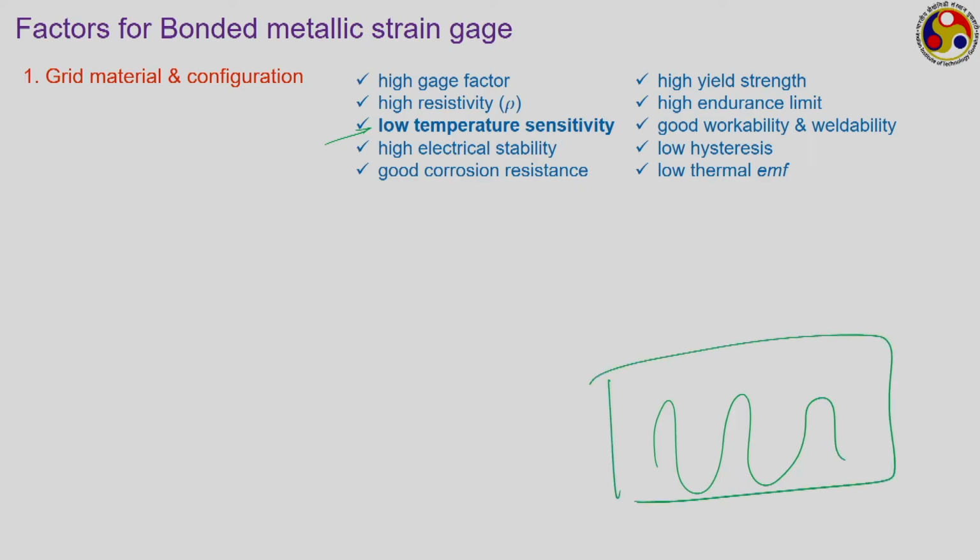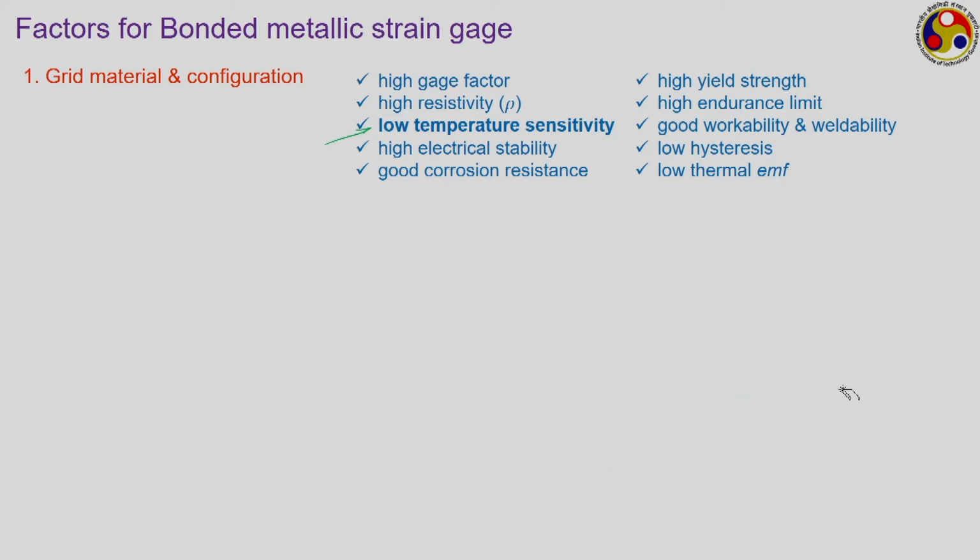They are generally fixed by adhesive or some other kind of mechanism. Now, if the temperature increases, then the bonding between the wires and the corresponding backing material keeps on changing, that becomes weaker, thereby producing an additional strain on the resistor element. Now, your sensor generally is not able to distinguish this thermal strain from the imposed strain, thereby putting an additional factor in the final output.